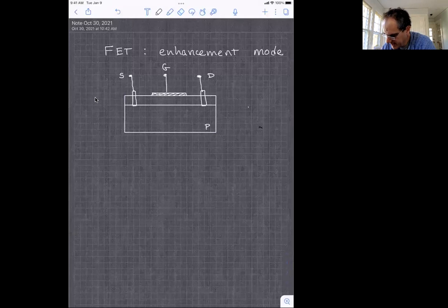And let's imagine now that the source and drain connectors, these were made by depositing metal on the surface of the semiconductor. But let's imagine that the metal contains within it donor impurities. So once the source and drain are deposited, if the semiconductor is heated up, those donor impurities will diffuse into the semiconductor and create small regions around the connectors, which are N-type. Okay?